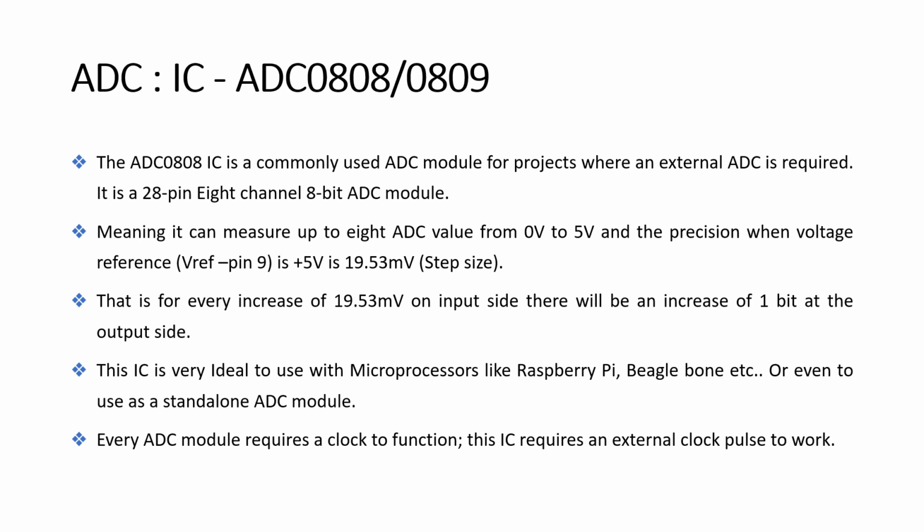This IC is very ideal to use with microprocessors like Raspberry Pi, BeagleBone, etc., or even to use as a standalone ADC module. Every ADC module requires a clock to function. This IC requires an external clock pulse to work.